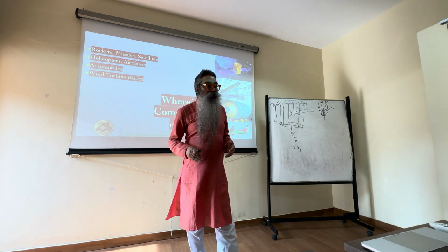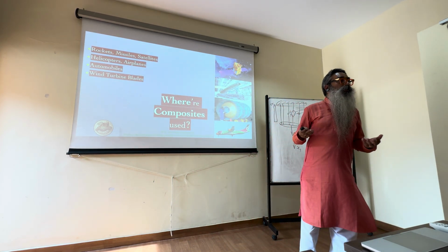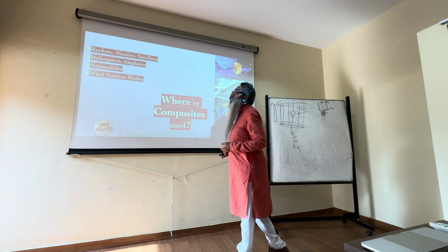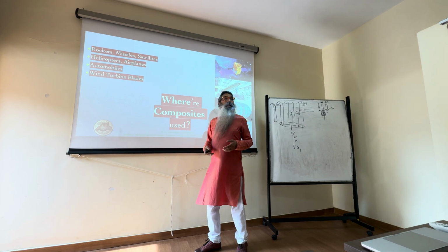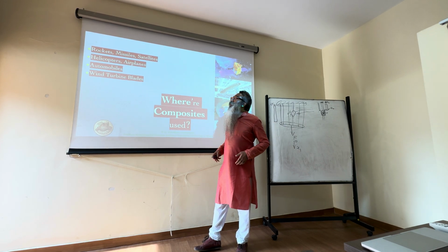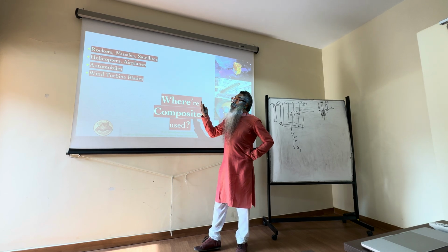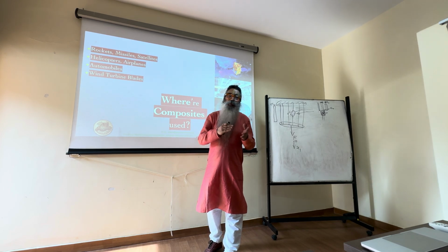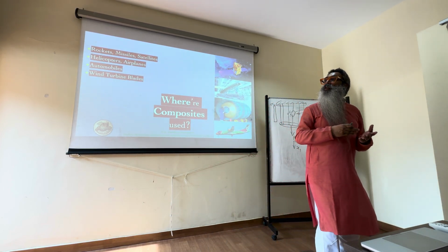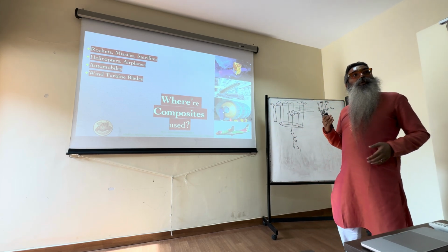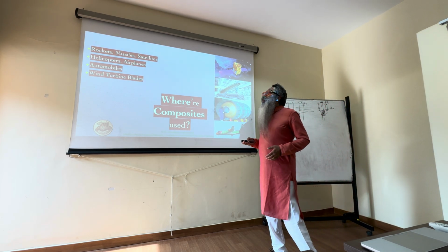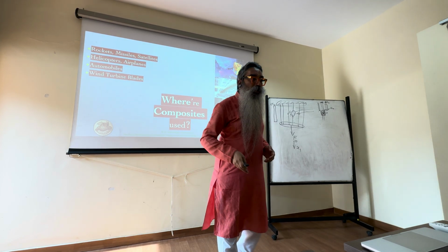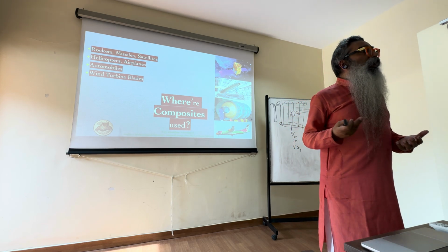Then static applications on the ground, wind turbine blades, because there is a lot of interest in renewable energy. Huge wind parks are coming up all around the world. The Scandinavian countries are historically famous for that because of their high wind speeds and also the kind of technologies that they have developed and patented over a long period of time. India is also going really big in terms of solar power and wind power. So wind turbine blades are really massive, huge, running into many meters of length, and if you make them out of metals, the weight is going to be phenomenally high and the stresses are going to be very large because of the centrifugal forces, etc., and therefore composites are very extensively used there as well.